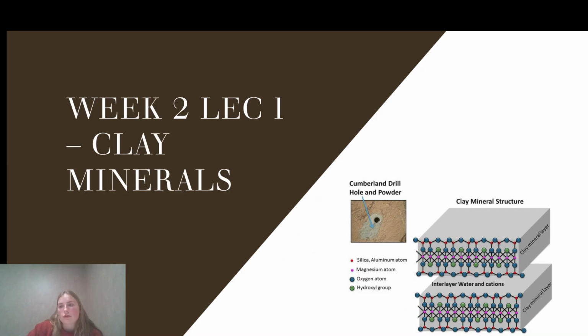Then we move on to week 2. So the first thing in week 2 is clay minerals. Clay minerals can seem a little overwhelming to start with because it seems like there's a lot of chemistry that's spoken about. However, the main purpose of learning about clay minerals is just understanding why a soil will behave the way it does when there's a large enough amount of clay in the soil. So when clay is about 30% or more, that's when it will start exhibiting the engineering properties of clay, to make it plastic and cohesive.